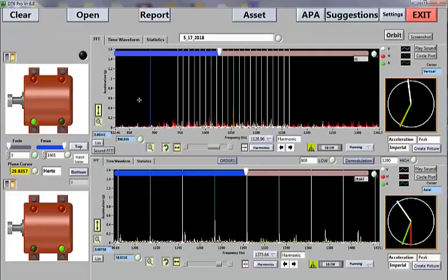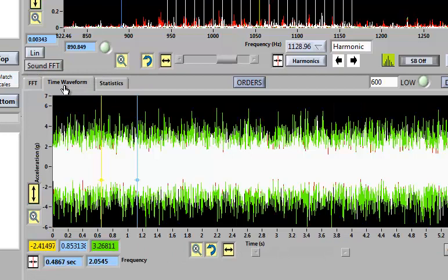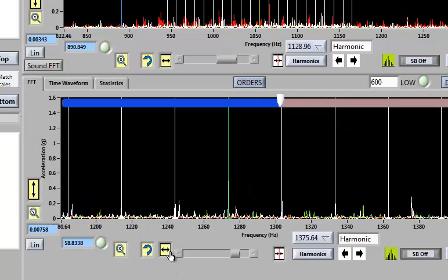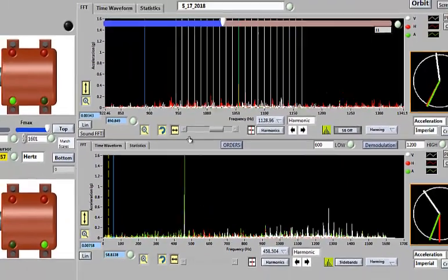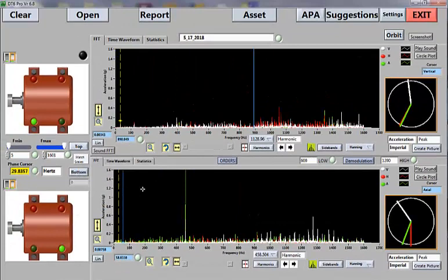But the other thing to keep in mind is that really in this vibration, the thing that seems to be of potential concern is that all the vibration we see here is really high up on the driven end. And so the first thing I would probably do after this is to try and run a resonance test or a bump test or something to see if any of these frequencies are resonant, especially this guy.